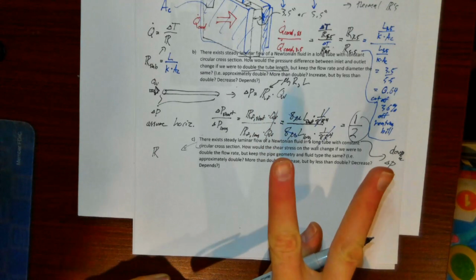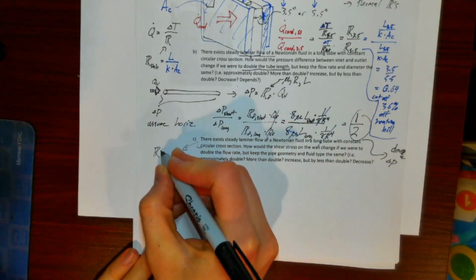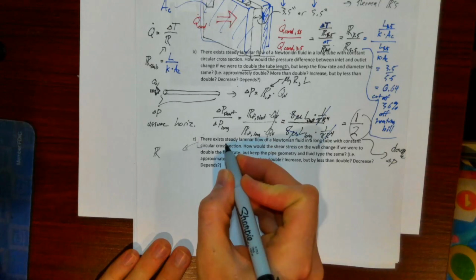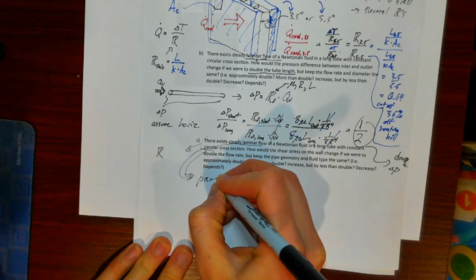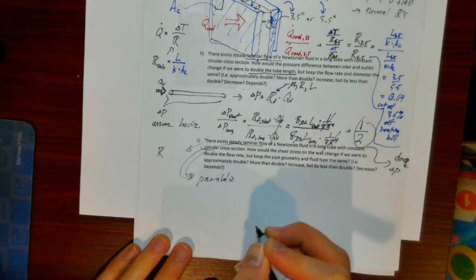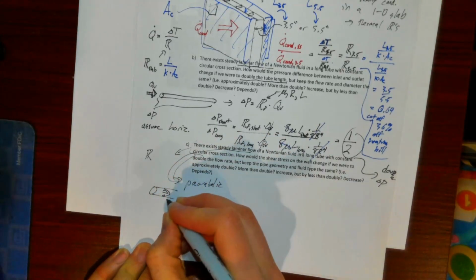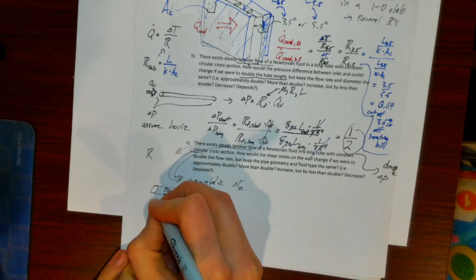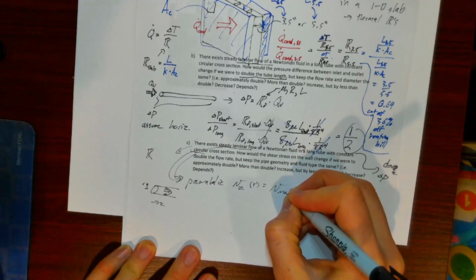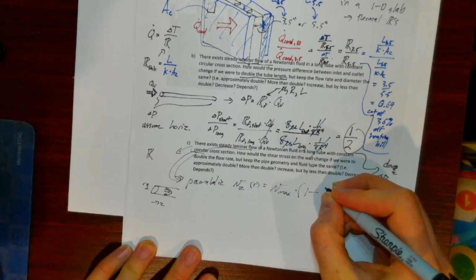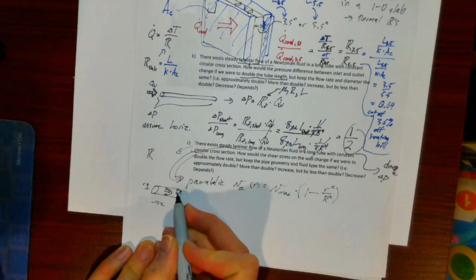So it turns out there are basically two ways to approach this problem. Let's consider the first case. The first one is actually not going to be fluidic resistors. If we know we have steady laminar flow in a circular pipe, we're going to have that parabolic velocity profile, where the z velocity as a function of r is going to have some v max in the middle, and it's going to be parabolic, so it's going to be 1 minus r squared over big R squared, where big R is the radius of the whole pipe.